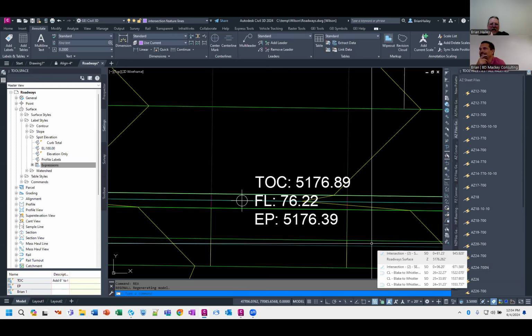I've never seen it where every spot elevation has an elevation, a northing and easting. It depends upon what it is you're trying to do with the spot elevations. So we typically had a horizontal control drawing and then a grading drawing. So the horizontal control drawing would lay out the locations of the features. And then in the grading drawing, it would then label the elevations of those features. Right. So that's the way we've always done it. I don't know. Does anybody else have good thoughts on this?